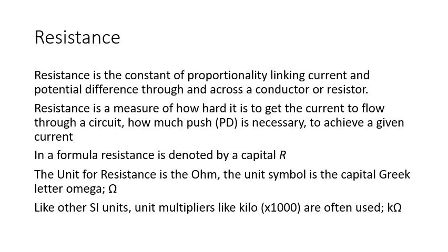And like other SI units, we can use multipliers on the top. It's not at all unusual to come across questions that contain kiloohms. In fact, when you're doing electronics and things, your resistances usually are kiloohms. Ohms, 2, 3, 4 ohms, are actually really, really unusual resistances because the current going through them is too large, and it tends to get the things far too hot. So we tend to use kiloohms quite a lot. You could have megaohms, you can have milliohms, same as all other SI units.